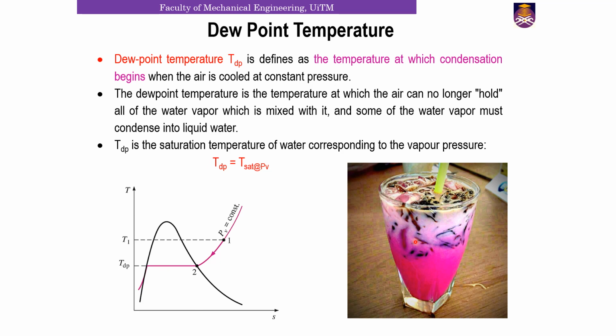This moisture capacity is the maximum amount of moisture the air can hold. After a while, the moisture capacity of air equals its moisture content. At this point, the air is saturated and its relative humidity is almost 100%. Any drop in temperature will result in condensation of some of this moisture, and this is the beginning of dew formation that you see on the grass.